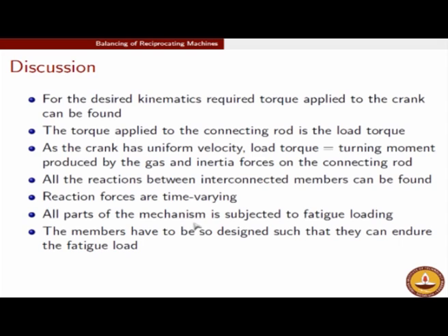But if the crank is moving at constant speed, the load torque has got to be equal to the turning moment. Turning moment is the moment which is making the crank move because of the gas forces. So turning moment is that moment which is coming because of the gas forces and the inertia forces, and the load torque is that which is resisting that moment.